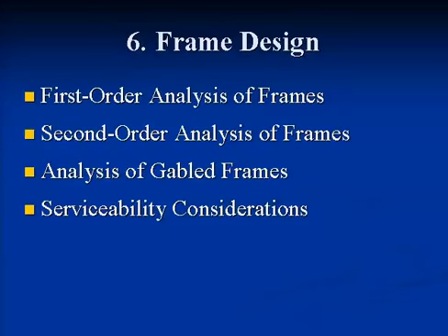So there's a section on frame design. This is oriented to a large extent, to some extent, to the metal building people. It discusses some of the issues of modeling with tapered members. There's some interesting things. You get curved neutral axes with unsymmetrical sections that turn up. Some discussions of second-order frame analysis issues, some special issues on gabled frames that the metal building people run into. That is a gabled frame with no support at the center where the frame spreads out as it's gravity loaded. It has some little different characteristics, and a very small discussion of serviceability.